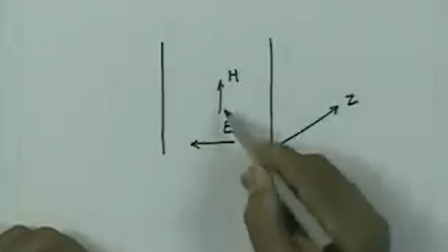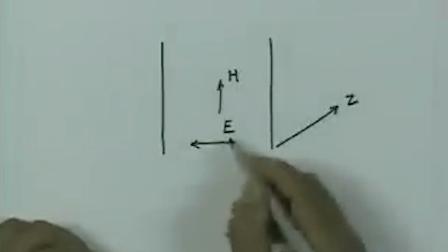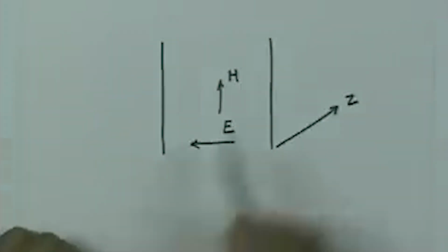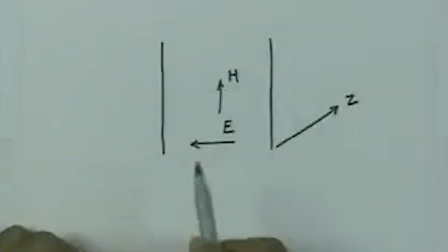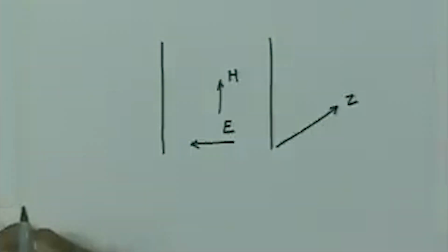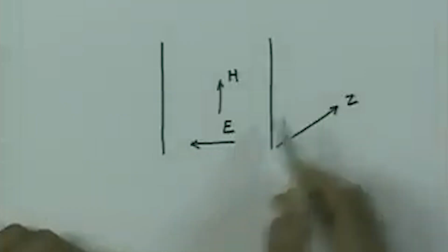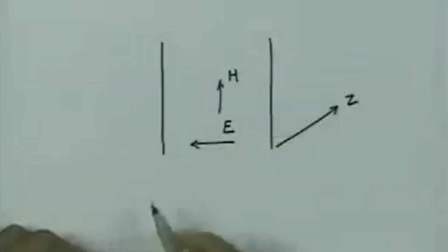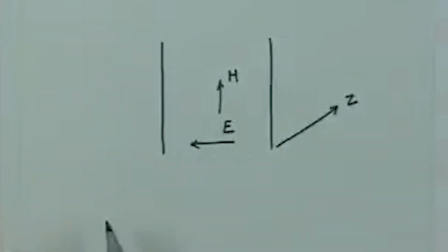and then this wave travels without any variation of electric and magnetic fields as we saw earlier, because neither H requires a boundary condition to be satisfied which is tangential. So, you can always have surface currents, nor the normal component of the electric field needs any boundary condition to be satisfied, because you can always have the surface charges induced to compensate for the normal component of the electric field.